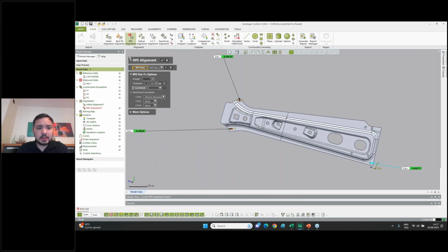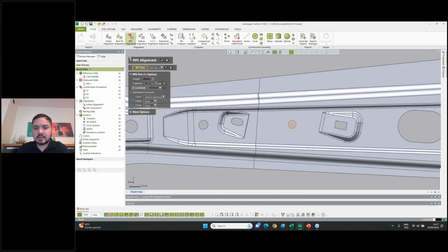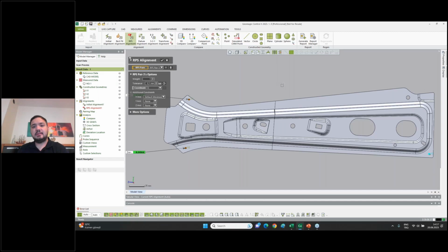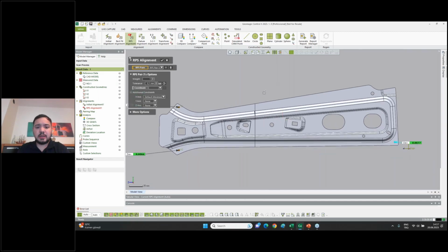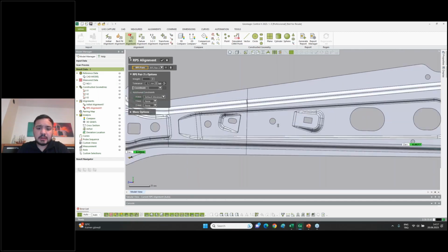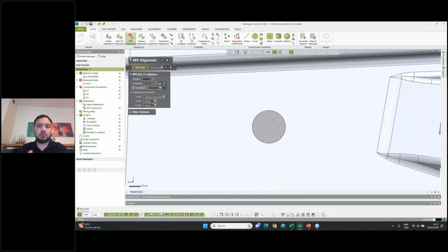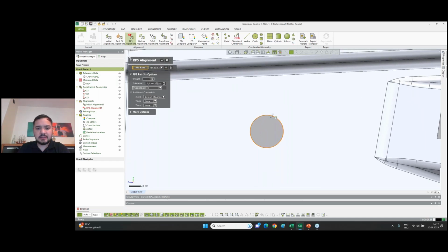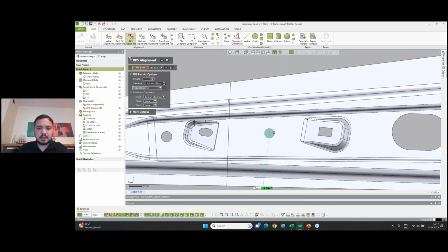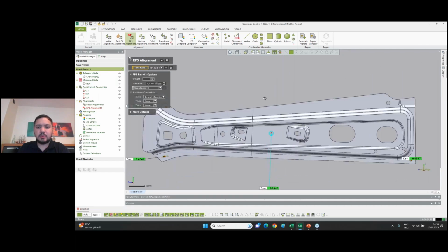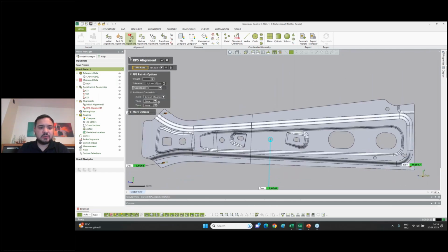After doing this, I need to use this hole as the Y and Z axes to do my alignment. But as we talked about before, I don't need to create a circle because Control X easily recognizes the geometry of the part and automatically pairs the measured one. So I just click the CAD model face, and it's also automatically paired with the measured value.